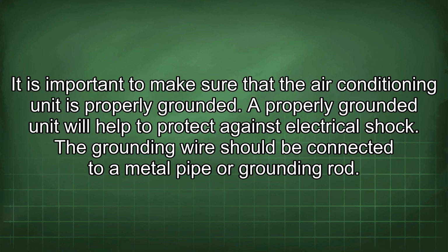It is important to make sure that the air conditioning unit is properly grounded. A properly grounded unit will help to protect against electrical shock. The grounding wire should be connected to a metal pipe or grounding rod.